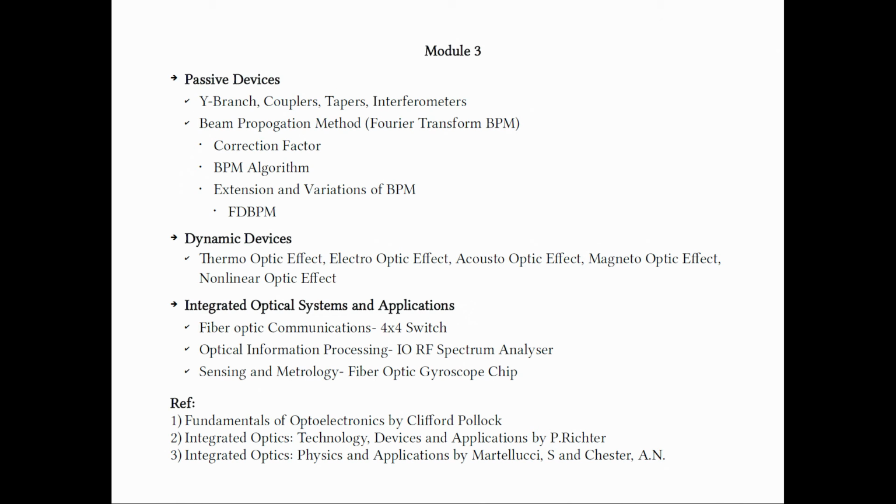bulk and integrated. In this RF spectrum analyzer, we have the RF field applied to the IDT pattern and optical fields propagating through these planar waveguides, and the grating is created by this RF field. The grating properties could be changed with the input RF field. Suppose the RF field contains a broader spectrum, then all the components result in gratings. We can say that there is a superposition of all these gratings resulting in a particular refractive index variation pattern.